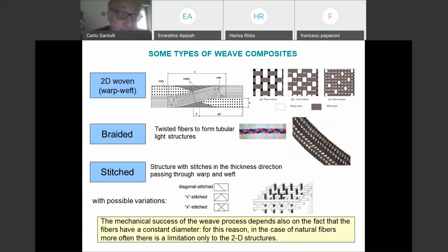Since they are not completely cylindrical, there might be some variation in the amount of voids I have in the material. Voids are important because if I have to put them into resin, then the amount of resin changes, and the availability of a good phase also might not be always sure, because voids mean that the resin can penetrate better in some places, not so in other places, and therefore I need some adjustment, some treatment in some cases. In natural fibers, in lignocellulosic fiber, I definitely may need some treatment.